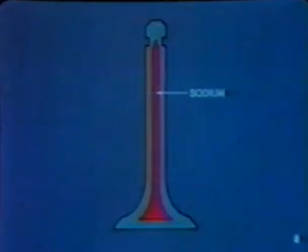So some exhaust valves have hollow stems filled with sodium, a liquid metal that conducts heat very readily. When a sodium valve is discarded, it should be buried, never cut open, because sodium burns violently in the air.